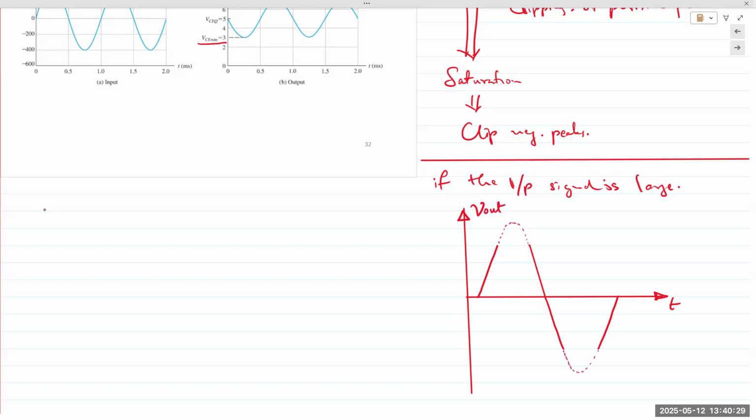And you may have observed or noticed this when we did the experiment in the lab for the BJT amplifier. When we provided a bypass capacitor across the emitter, the gain was larger. Because the gain was large, the signal is amplified more than without the capacitor. And so you could see clipping or distortion at the top and at the bottom.